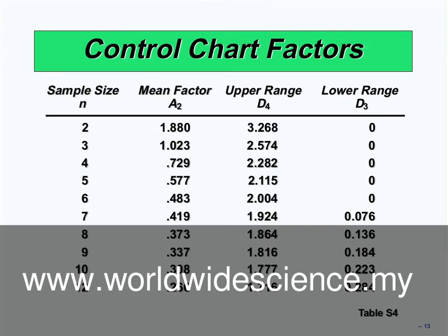Yes, exactly. The X bar chart and the R chart are tools that can be used by operation managers to see whether the process is under control or not. If the process is not under control, it means that the production has defects or a problem, and the process should be stopped and the machine and the labor checked to find the problem. I'm telling you how you can work with this chart to find whether the process is under control or not.